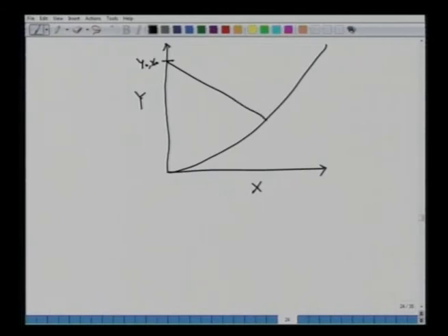We have this number, so the concentration of the wastewater stream decreases till we reach this equilibrium exit concentration, which is x1. x1 is 565, corresponding to which we now have 3.3. So this y0 was 9.6. We have brought it down from 9.6 to 3.3. We have to get down to 0.96. So this number is fixed here, 0.96, and corresponding to this value x2 is fixed at 270.